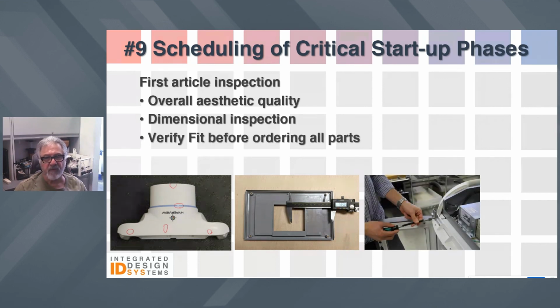And then you want to verify that all the parts that are going to be assembled, whether they're sheet metal parts or PC boards or whatever you have going together, are all fitting together properly. And you don't want to order all these things at the same time, because if you ordered, let's say, 5,000 PC boards and they're already made and in inventory, and now the molder finds that the molded parts are out of spec, it's going to cause a major tooling change to revise the tool to change, let's say, boss locations, etc. And it's going to be very expensive. Let's say you made a mistake. Many reasons to take into account here. It's easier to change the whole location of a PC board versus changing a tool.